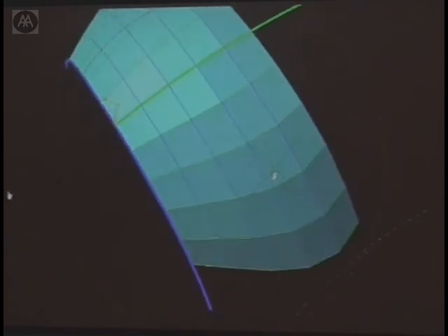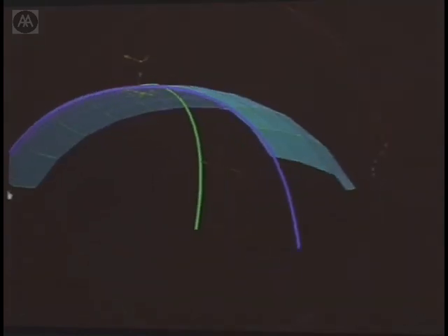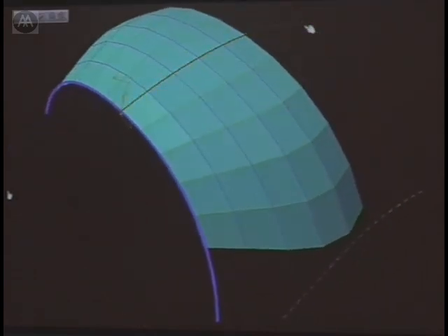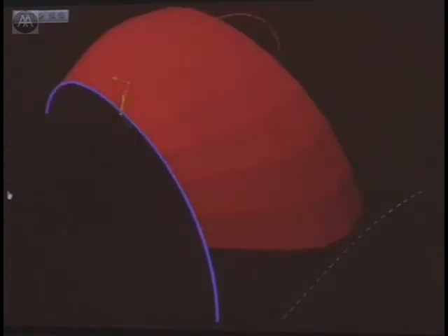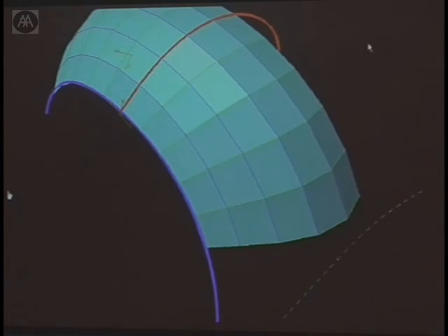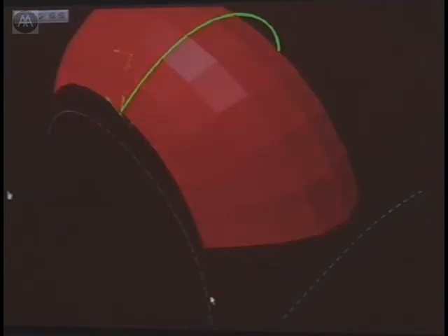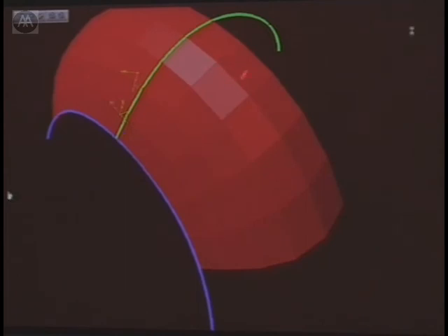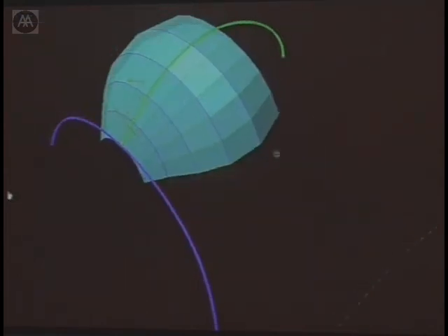And so we worked with Schlaich to capture some ideas that they'd been developing. We ended up even writing some scientific papers on this. I won't really go into the math of it. So suffice to say that these are what are called scaled translation surfaces, which means that by governing a certain number of control splines, you can actually get these surfaces that approximate any freeform surface, as opposed to being a torus patch or something more regular like that. And you're always getting these four-sided flat pieces of glass, these quadrilateral panes,